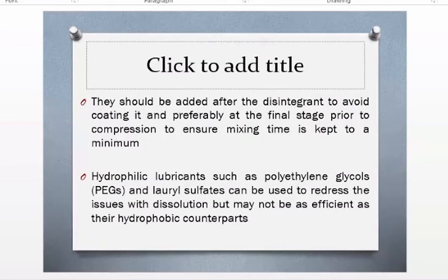Ideally, they are also added at the end of powder blending. So when you are mixing, or adding these lubricants, you also reduce the time of mixing. Usually mixing time is restricted to about 3 to 5 minutes, just to ensure that you don't turn the powder blend into a hydrophobic material.